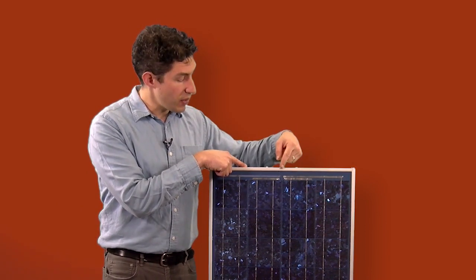For example, this module is made of 36 cells wired in series, 18 on one side and 18 on the other. They're electrically separated in the middle, and there's a break here. That break is where we would find the bypass diode that electrically separates the two sides. If one side of the module would go down, then the other side would be working. The downside to any bypass diode is that it lowers the operating voltage slightly, usually less than 1 volt. This small decrease, however, prevents the current and power loss that would occur. This more than makes up for the missing voltage. Bypass diodes are put in by the module manufacturers and are not typically serviceable.